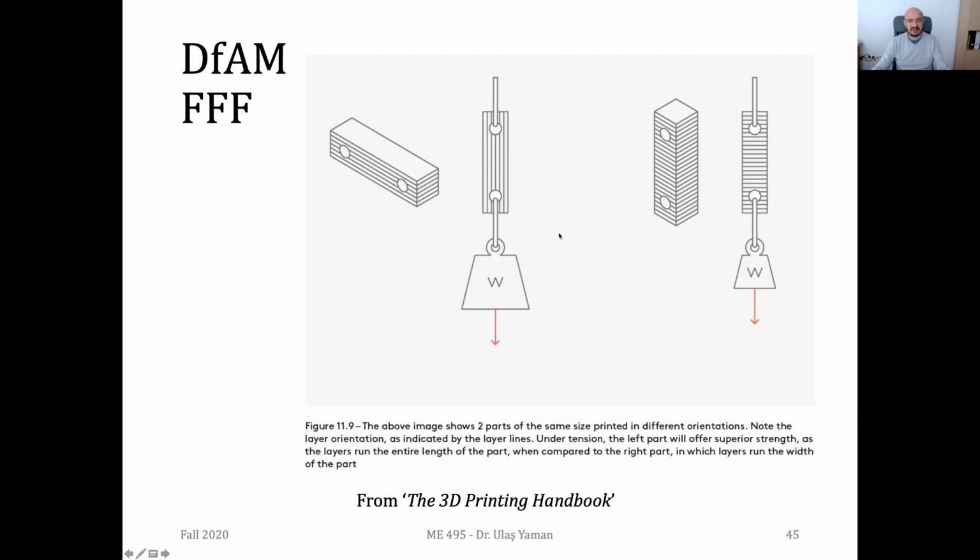We have many papers about this, and this is also engineering. By engineering intuition, you can simply say that this one will carry more loads, since the plastics in FFF are extruded in this direction. So we don't need to use bonding forces while we are carrying this weight. But if you look at the right-hand case, in this application, the bonding between the layers is the most important thing, since they are responsible for carrying this load W.